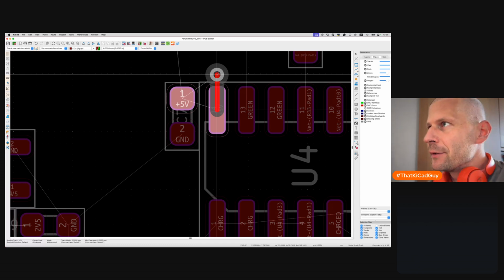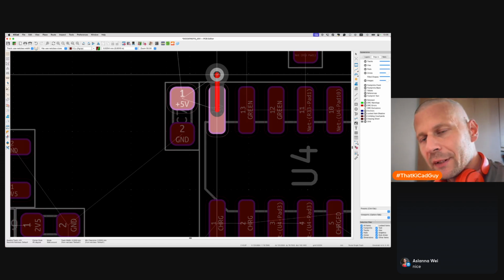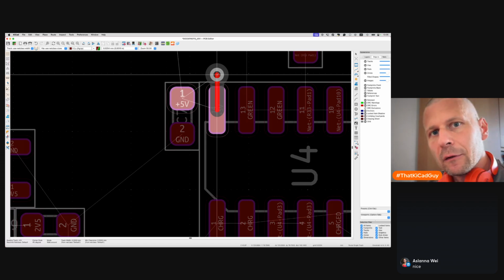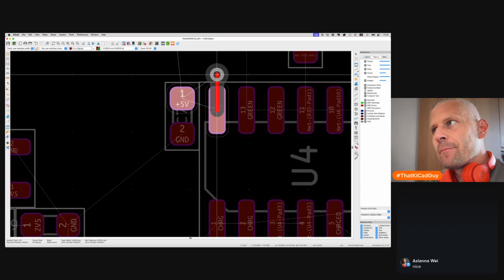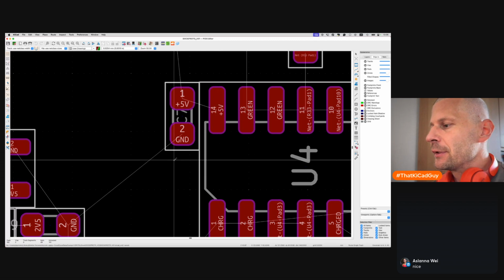Because when the vias are unmasked completely, it's a tunnel for the solder, and when there is no solder mask in between the via and the pad, there is a channel for the solder. So this is the reason.